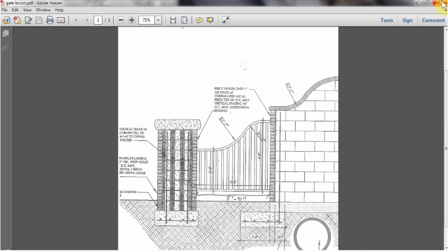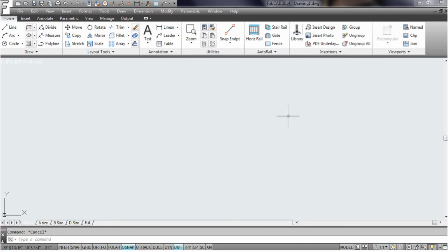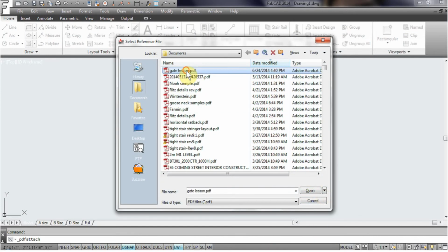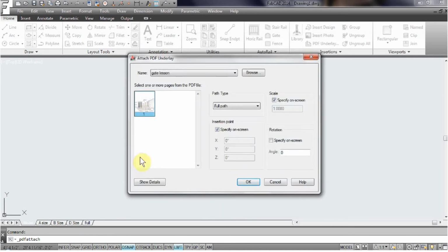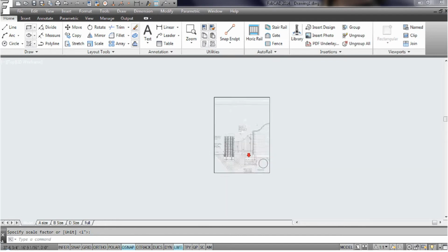you a PDF of a custom fence section that you see here. So what I'm going to do, I'm going to close out of the PDF here and open up FabCAD. What we're going to do is we're going to bring the PDF into the drawing. We're going to use PDF underlay to do that. So there's the PDF. I click OK, put it on the little workbench here.